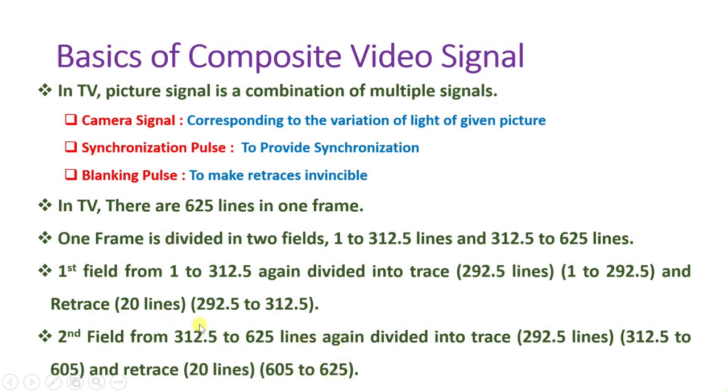Blanking. The composite video signal contains blanking pulses to make retrace lines invisible, namely by changing the signal amplitude to black when the scanning sequences produce retraces. All image information is cut off during blanking time. Normally, retraces will occur during the blanking time.